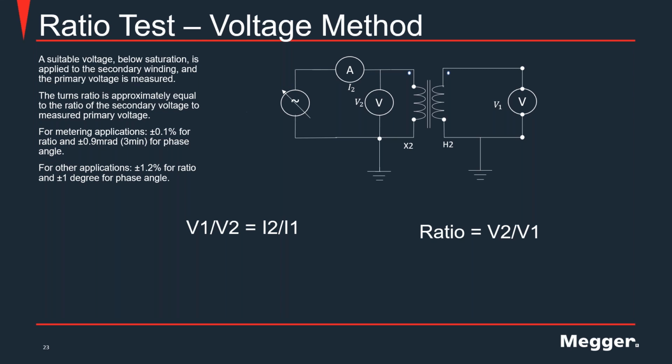Here we are using some voltage that's somewhere between 0 and the knee point, and sometimes you're using half of the voltage of the knee or even lower, and the amount of energy that you're injecting is very low because we are only talking about the excitation current at that point. And why would you use the current method if the voltage method is available? So that would be the answer.